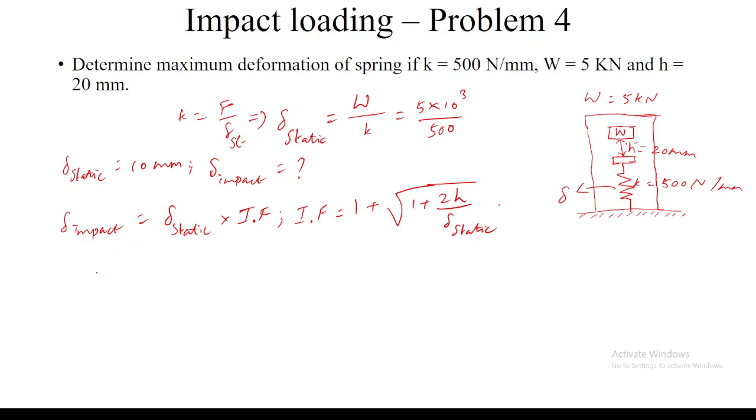Can you find the impact factor and say what it is? 1 plus under root 1 plus 2. What is the h here? 20 mm, divided by delta static, which is 10 mm. Can you find the impact factor and say?